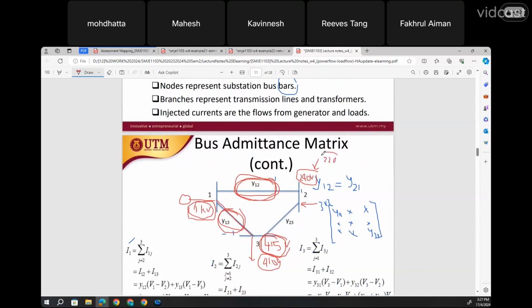Okay, once we know what is the voltage value over here, we know that we need to have a higher value of power generated by the generator so that it can match back to the 240 voltage requirement for the ideal case. And to get 240 is ridiculous maybe, because this impedance is always there, transmission lines are always there, your wire is always there. So you're never gonna get this nominal value of voltage at the bus bar.